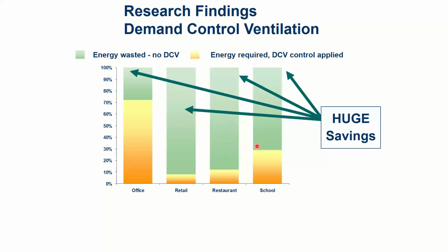To give you some examples, this is real projects but kind of averaged out. Here's some office projects here, the first one showing, I'm going to call that 28% reduction in energy on average by just tracking the people not being there. Basically, during the daytime, it's 28% unoccupied on average. That means sometimes it's half unoccupied, other times it's 98% occupied. But 28% reduction in outdoor air needed that I don't have to heat, cool, filter, and ventilate.